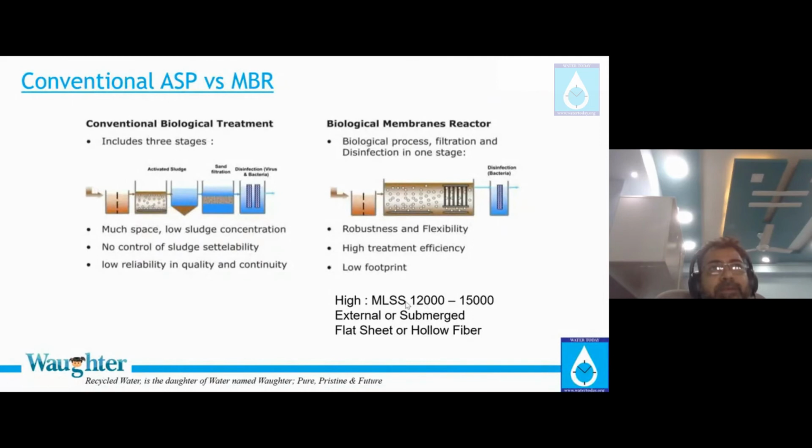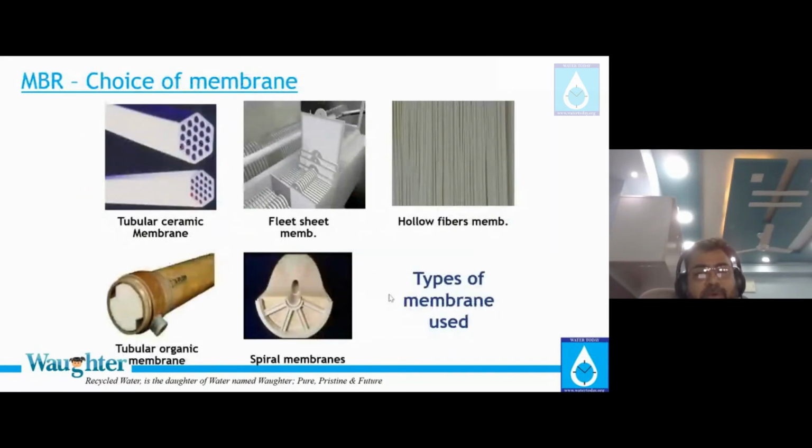There could be some clients who will say, no, from an aeration tank design perspective, keep the MLSS not more than 5,000, because if anything goes wrong with the MBR, I can still use my existing clarifier. Because at 12,000 MLSS, if anything goes wrong in the MBR, and MBR repair or replacement will take 4 days, you cannot say, okay, for the time being, you give your sludge to the activated sludge clarifier reactor which you were using earlier, I'll settle it there. No, it will not settle there. I'm telling you right now, it will not settle there, and it will be a big problem. So sometimes, customers are the right people who give the advice on how much MLSS they want to maintain.